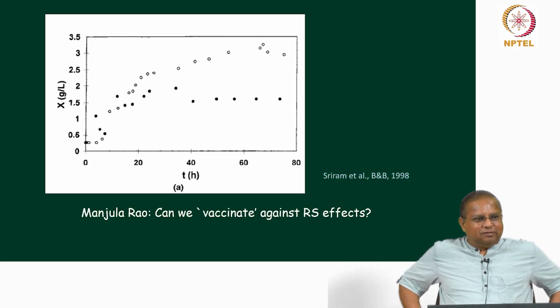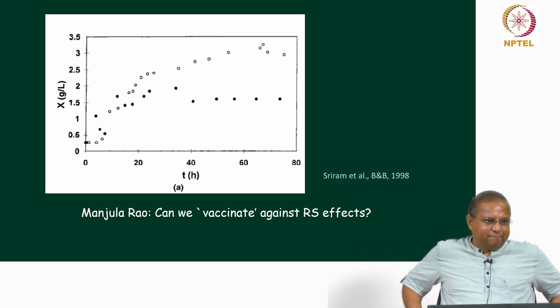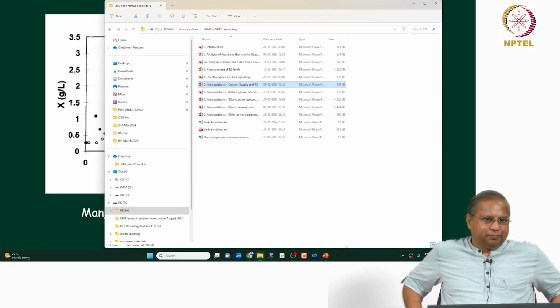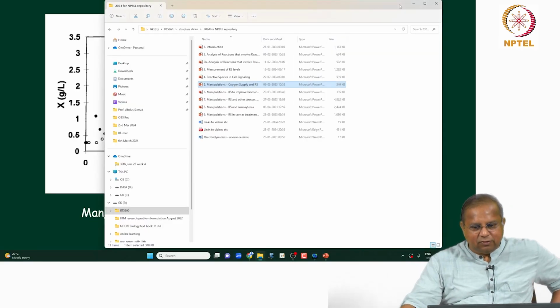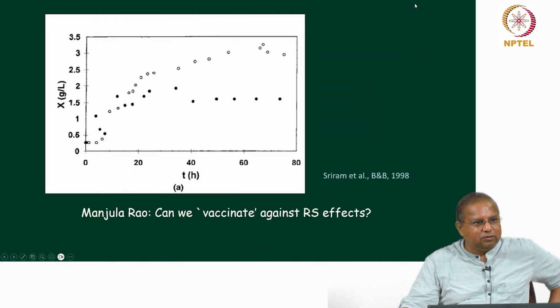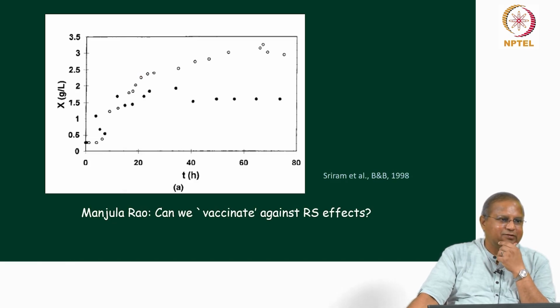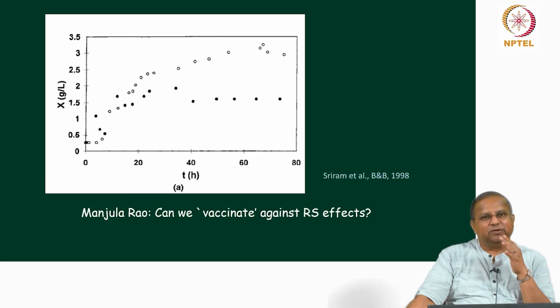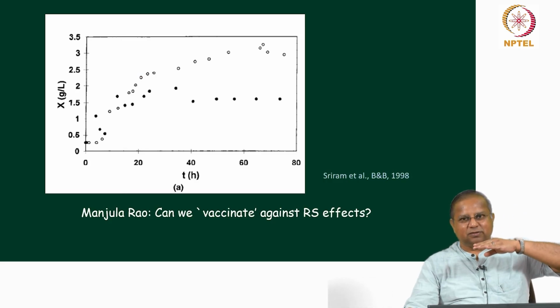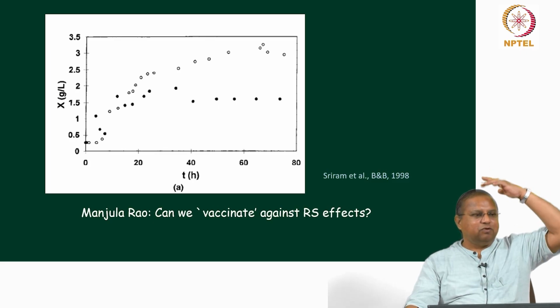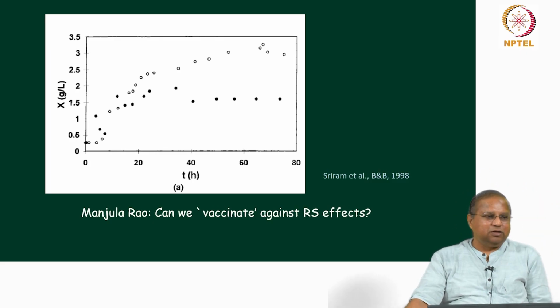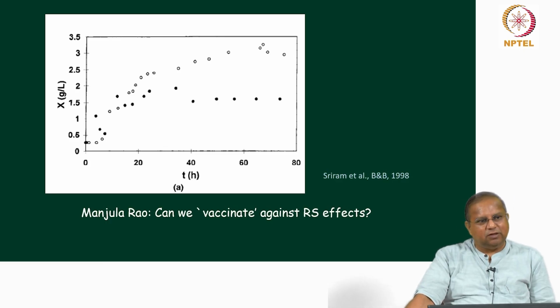Questions, comments. One point in the paper: the volume of H2O2 added was 30%. No, less than that. No, 24 ml out of a liter, which is insignificant. We didn't want to arrive at a situation where whatever you add increases the volume of your reactor too much. It will lead to dilution and other unnecessary things during operation. So we didn't want that, and I think we used 30% concentration.